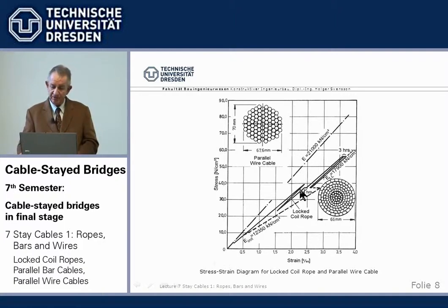Then, when they are installed, we stretch them, or we do it on a bench. We can pre-stretch them. So we stretch them up to their highest service load, dead plus live, let go, stretch, let go, it stands for 3 hours. So then the wires get tight and we get this slack out. And so then the modulus of elasticity increases from 12 to 18.